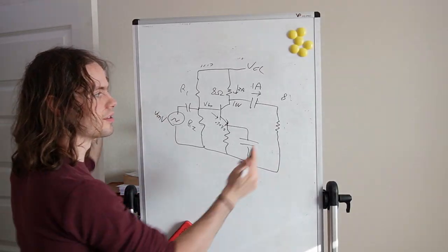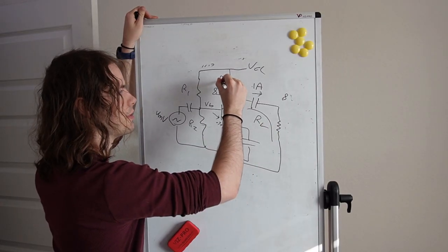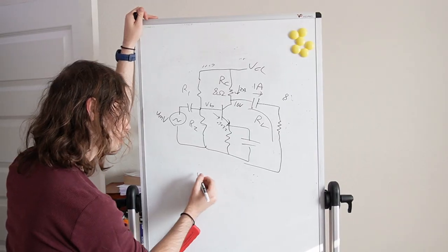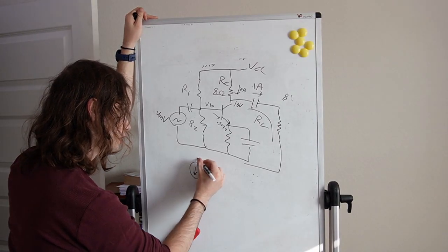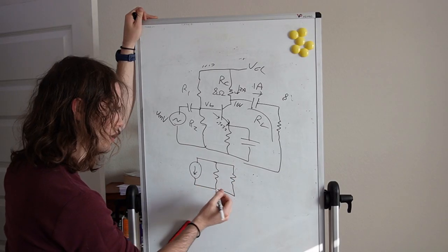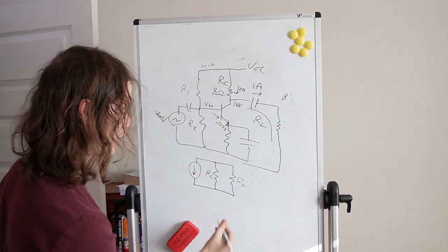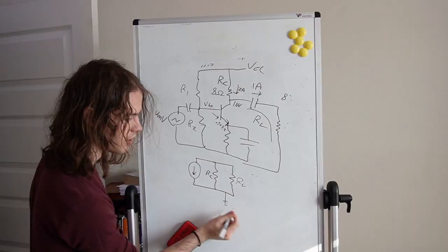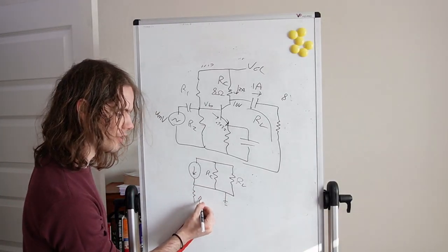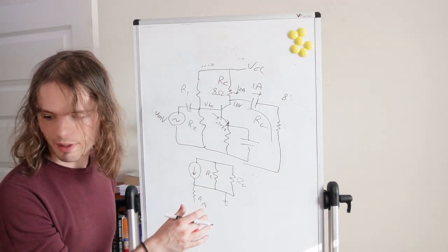So let's model the impedances. Well, over here, this can be modeled as, we'll say, R load, and this can be modeled as RC. When you do AC analysis of a BJT, it looks something like this. R load, RC. The main point is that you will have RC, RL, and I think here RE would be down here, but we'll ignore it for now. The main point is that you have a certain amount of...